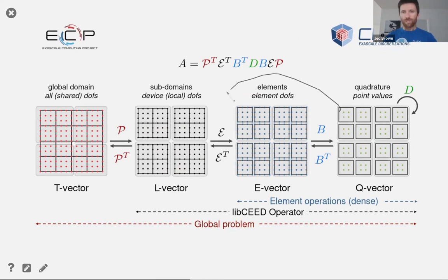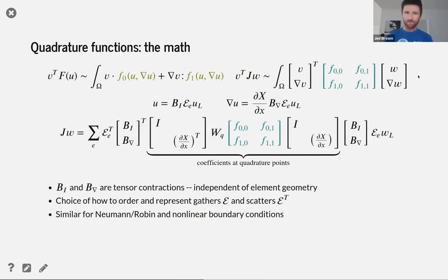And so we can do lots of transformations in this kind of middle part, fusing and being smart about various operations here. But there's a bit of the user code that needs to be defined of what happens at quadrature points. This is where we define the physics of the problem. And there's some interesting choices that go into making that efficient. So when solving PDEs, we often solve nonlinear problems. And so for the nonlinear problem, we're creating some f of u, and there's a quadrature function that goes in here. These are things that the user provides in order to define their problem, or some higher level library that's more domain specific. We're very general purpose.